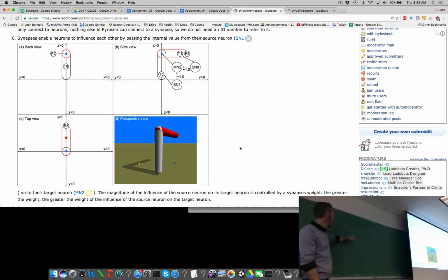The physics engine, however, is doing this using floating point values in your computer, which have a finite accuracy, right? So as you run this for enough time steps, there's a little bit of error that starts to creep in because it's approximating, it's not perfectly computing acceleration based on forces and masses, right? It's pretty accurate, but eventually those approximations catch up with the system, and this is not a perfect approximation of Newtonian mechanics, and it falls over.